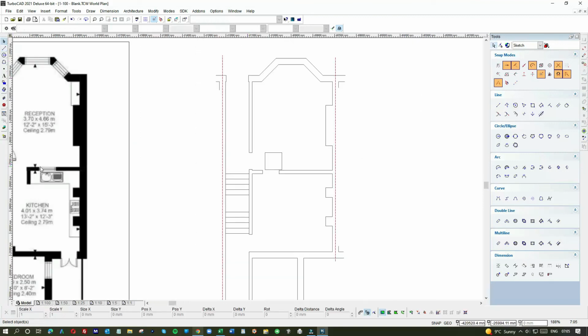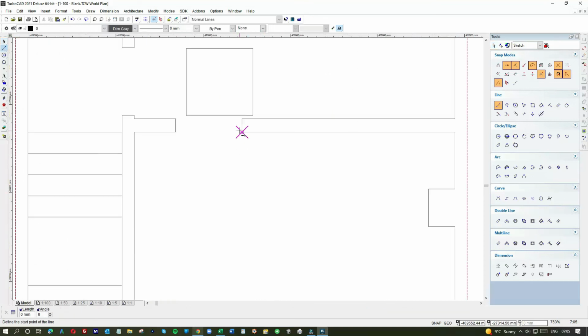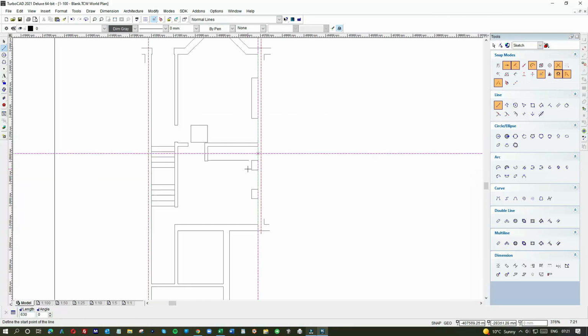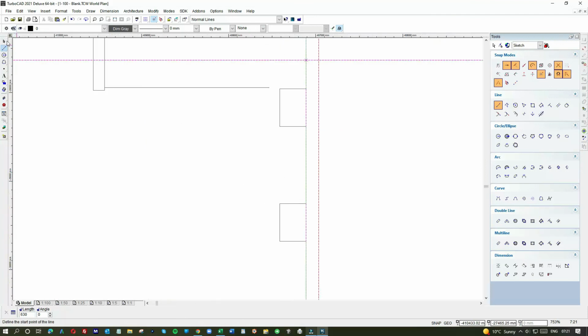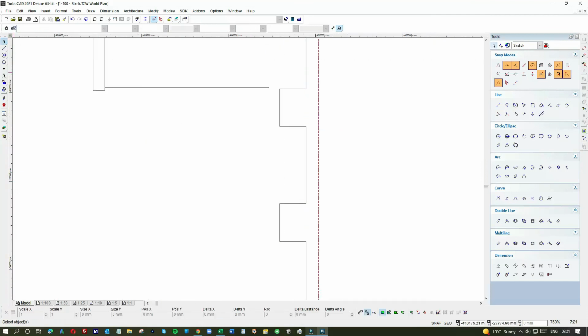Now here, what they did was the kitchen is there. They brought out a stud wall here. So let's do that. For the side wall, or the other half of the kitchen, again, come out 630. Let's just click off here for a minute. I haven't said it while I was doing it, but what we need to be doing is saving the drawings routinely.